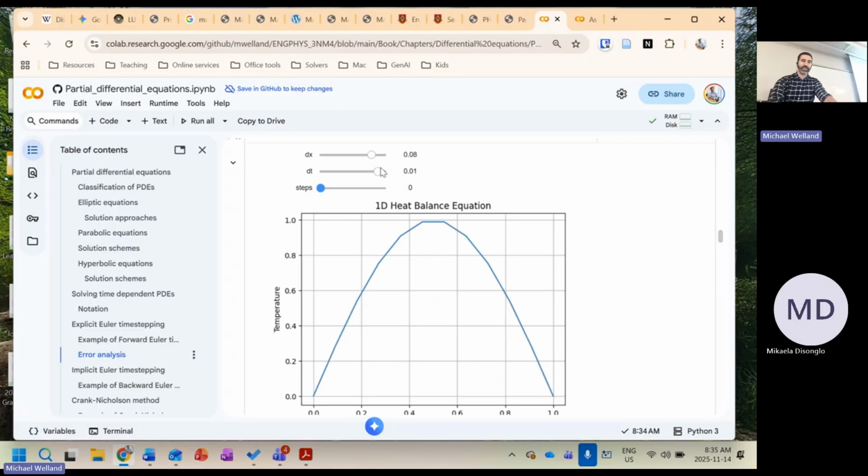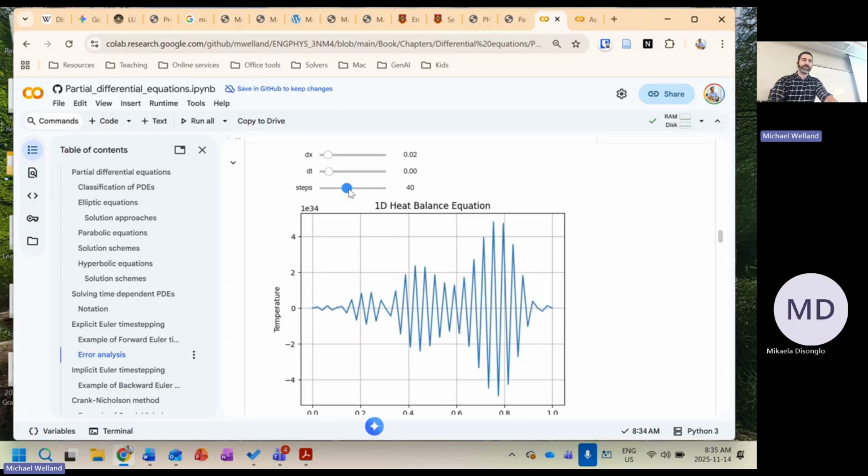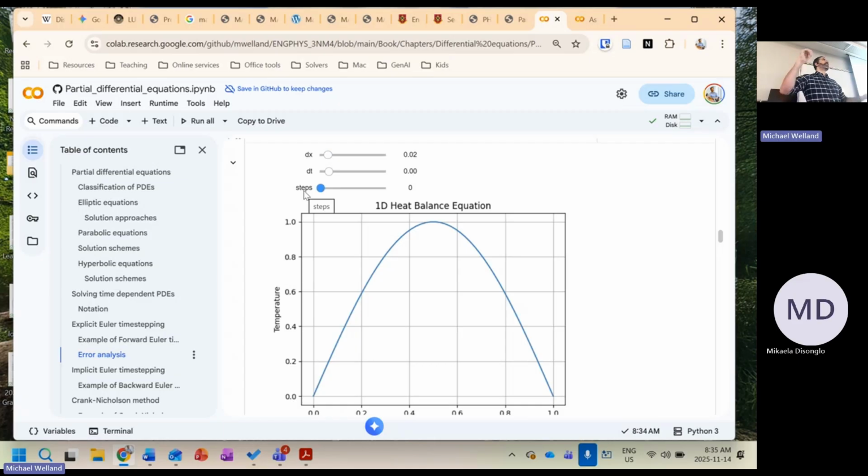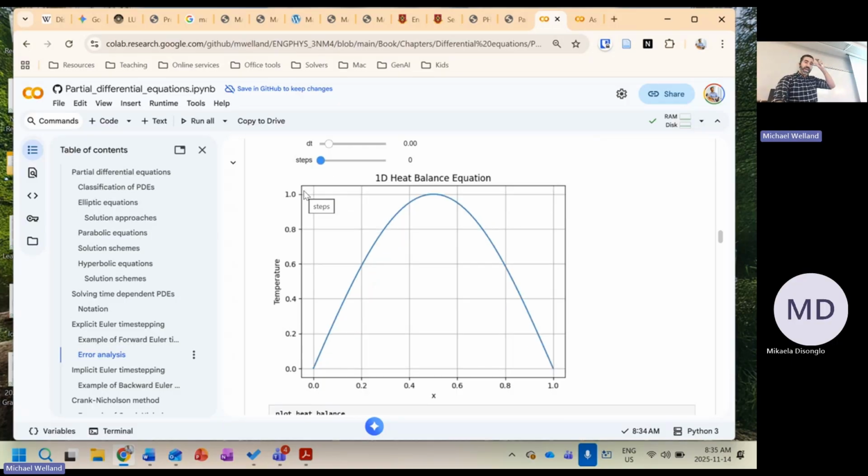Just by time iterations. Similarly, and disturbingly, if we try and take smaller spatial steps, watch the faceting of the curve, right? While I'm doing that, get smaller and smaller and smaller. The exact same thing happens, right? So smaller spatial steps will cause all this gobbledygook, and larger time steps will do the same. And both are kind of disturbing, right?